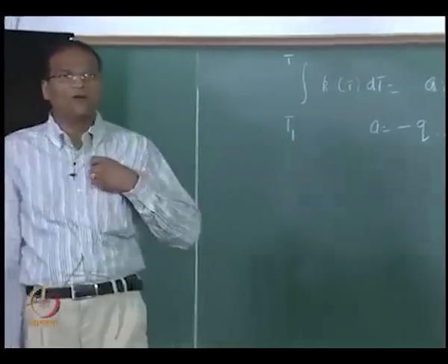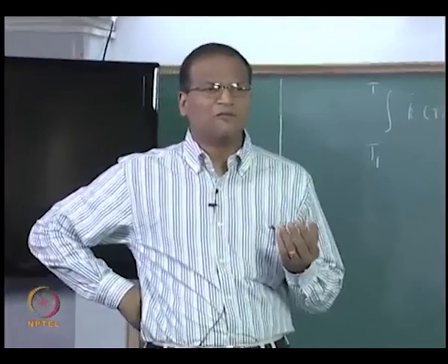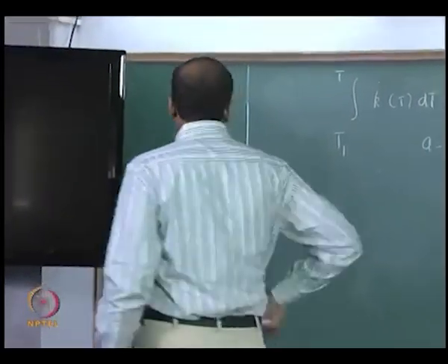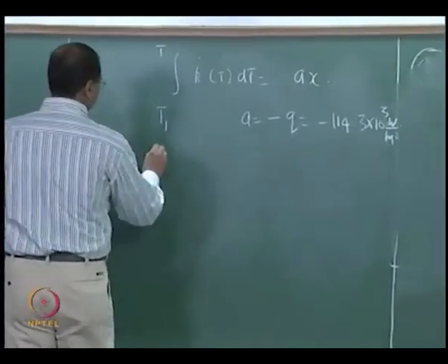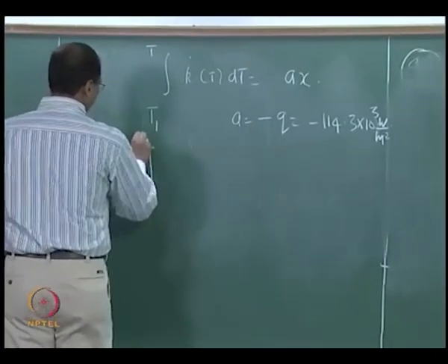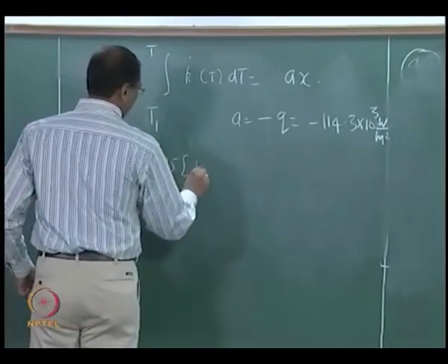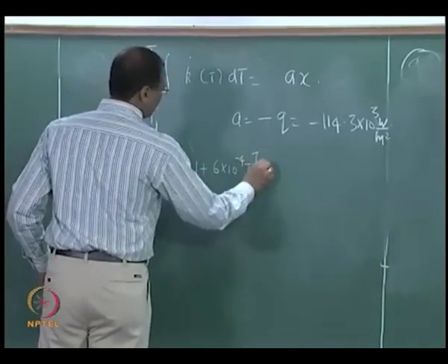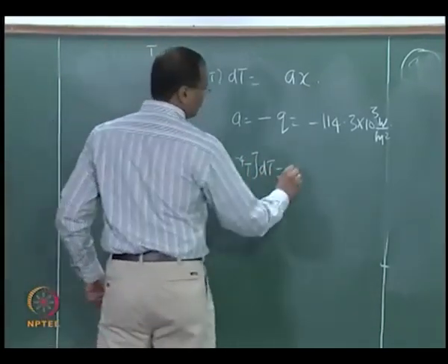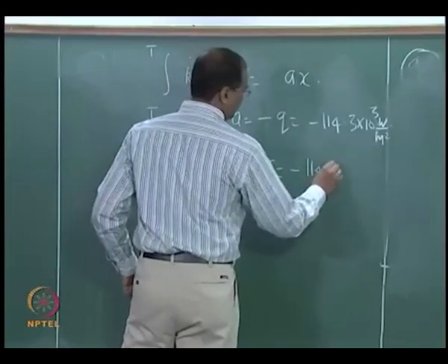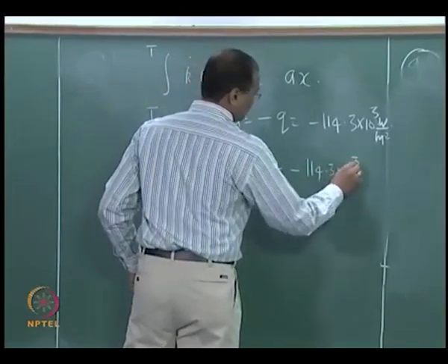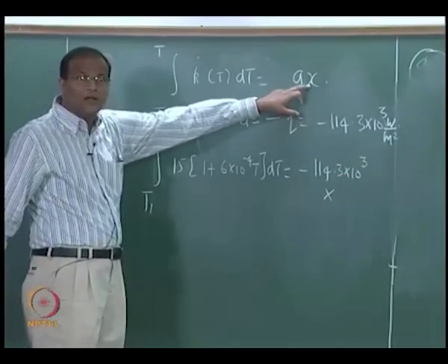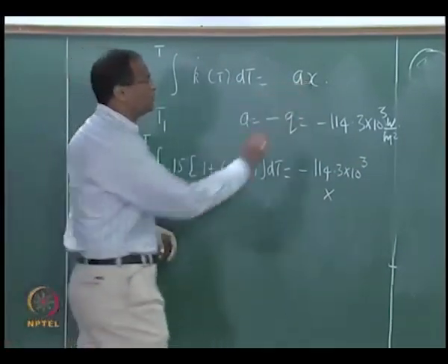One dimensional plane wall, no heat generation, steady state, whatever is coming from the left side has to go on to the right side. Where else can it go? So therefore, what is the x we want? X equal to 0.025, the mid plane.